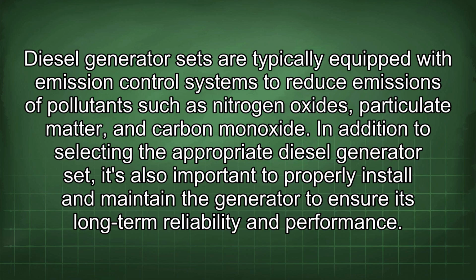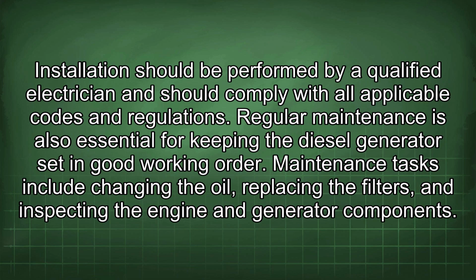In addition to selecting the appropriate diesel generator set, it's also important to properly install and maintain the generator to ensure its long-term reliability and performance. Installation should be performed by a qualified electrician and should comply with all applicable codes and regulations. Regular maintenance is also essential for keeping the diesel generator set in good working order. Maintenance tasks include changing the oil, replacing the filters, and inspecting the engine and generator components.